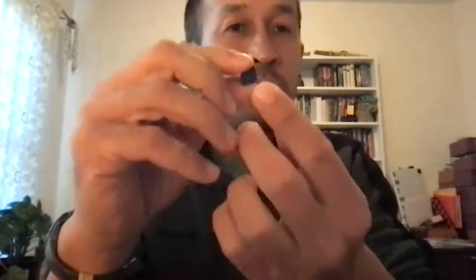So we have 5 volts going in and then going out to ground on the other side. By turning the dial, from the middle wire we can change how much voltage is coming out. It will be somewhere in between 5 and 0, depending on how much we turn it one way or the other. It can be a variable amount anywhere between the 5 and 0 volts that are there.